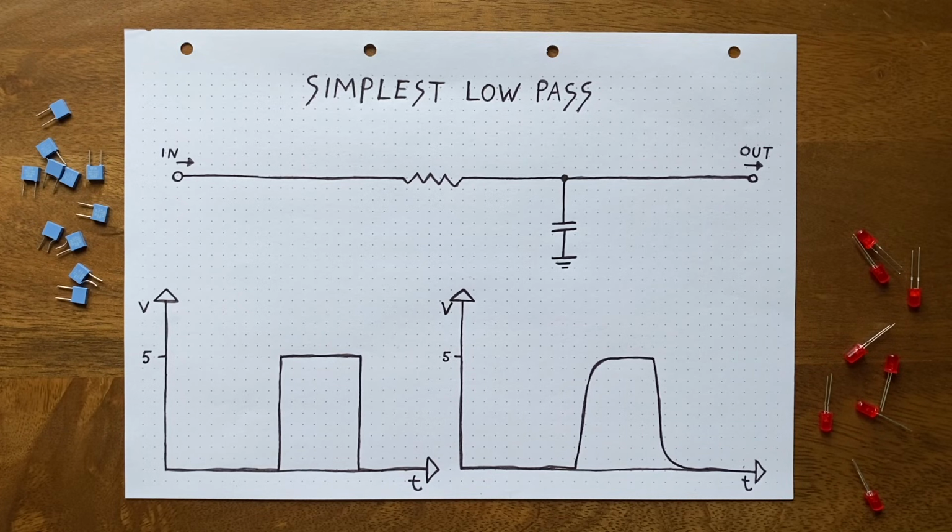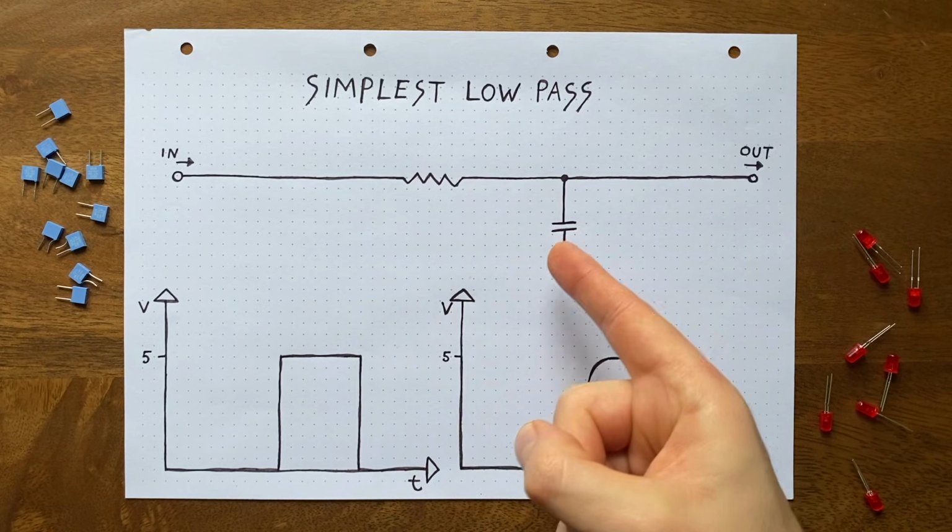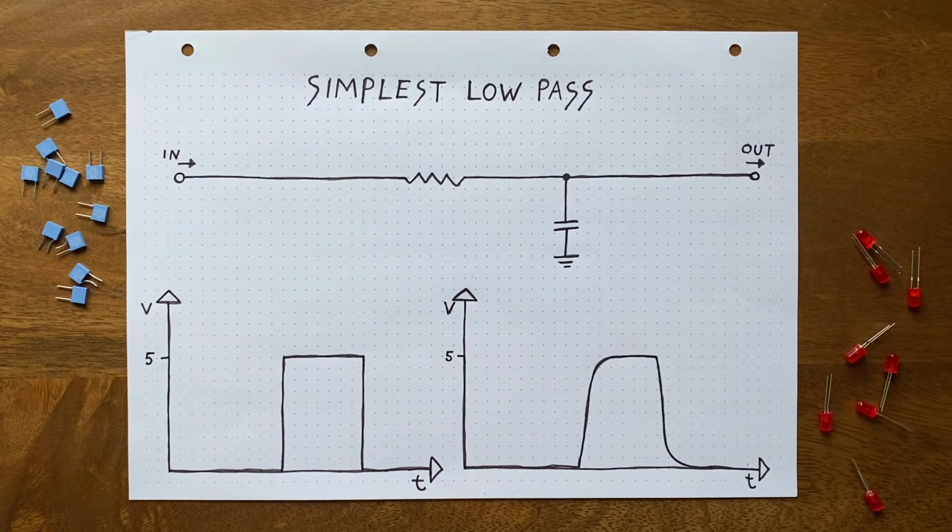But nevertheless, we can expect it to sound a lot less harsh. To try this out, we'll first have to decide on specific values for the resistor and capacitor. Since I largely tried to stay away from formulas, I simply tested a few value combinations and found that a 470 kilo ohm resistor and a 10 nanofarad capacitor work best for our purposes here.